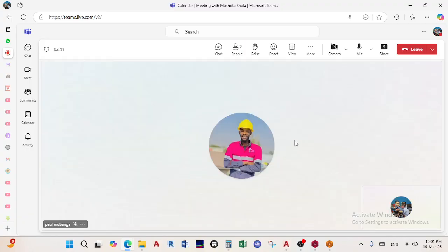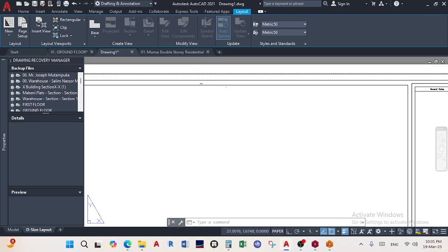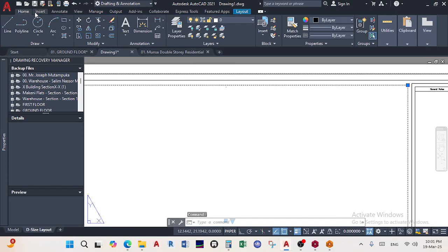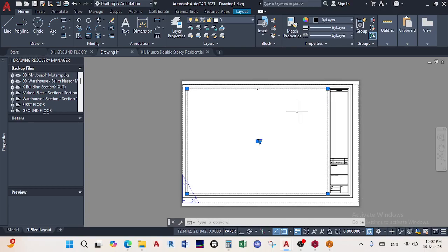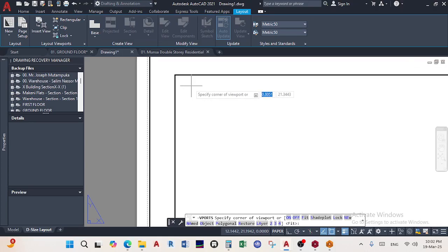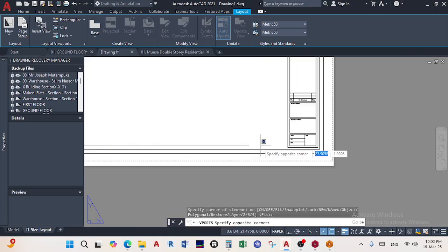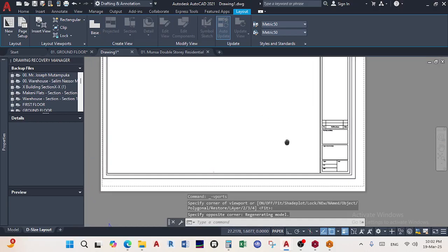Yeah, so like I was saying, here, this I can select it. You can name it as a viewport. I think I showed that. So for example, I delete if it didn't come, if your sheet didn't come with your viewport, don't be discouraged. Just go to this viewport, you select rectangular, you select the extents of your viewport, and then when you do that like that, you have your viewport.